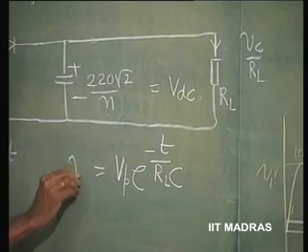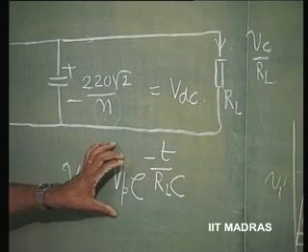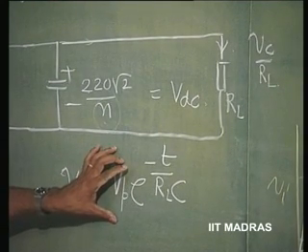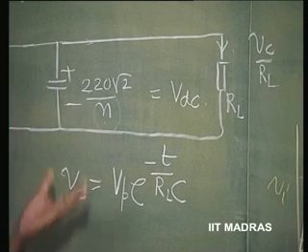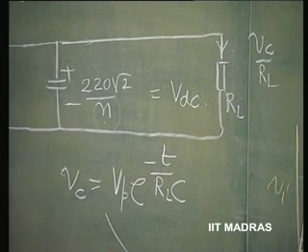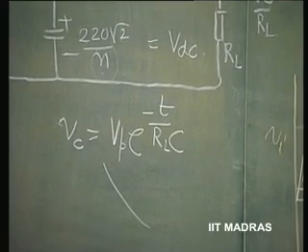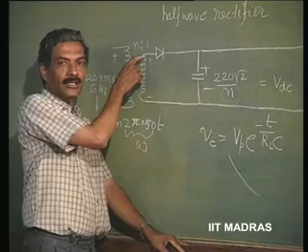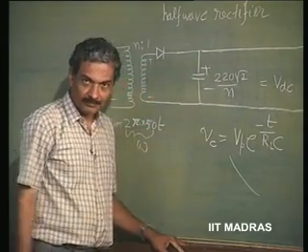So, this is the voltage across the capacitor at any instant of time, Vp being the peak voltage to which the capacitor was initially charged, and t equal to 0 is the time at which the discharge process starts, and then onwards the capacitor will discharge. It will keep on discharging until you start charging. The moment the voltage of the capacitor falls below the voltage of the input, the discharge of the capacitor starts.